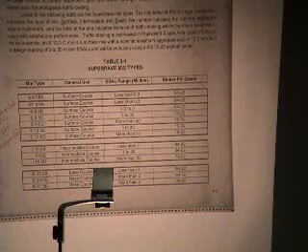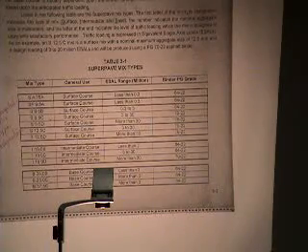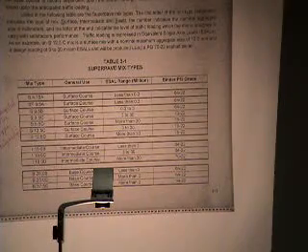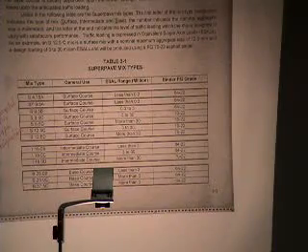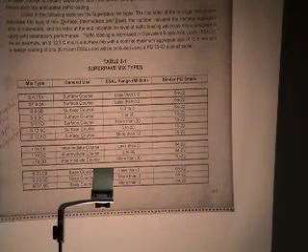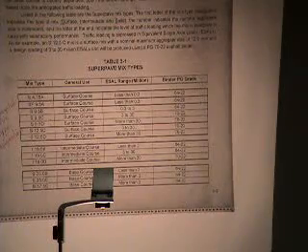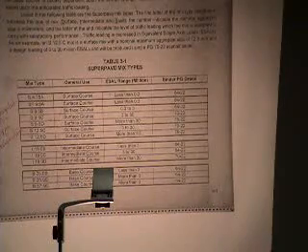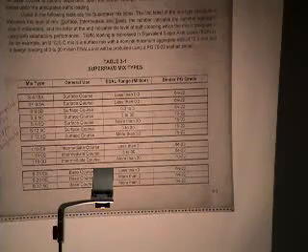But on the PG76, that's a polymer modified asphalt. They take something on the order of the PG64 and add polymer to it. That makes it real stiff, even when it's real hot, in hot weather temperatures. Very high performance asphalt, very expensive, maybe 2 to 4 times as much as PG64. So that really pushes that price up.